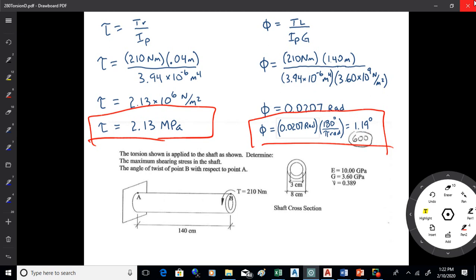What would happen there is you'd adjust your distributor cap and get advanced. Anyway, you used to time when the spark came to the cylinder on your car, and you used a strobe light, a timing light. There were two tick marks that would match up, and that was a pretty good example of this idea of twist. So if I put a mark right here, and there was a mark on these things, what the twist angle would be is this point would, and I'm really exaggerating it just so I could draw it in there, twist over 1.19 degrees.